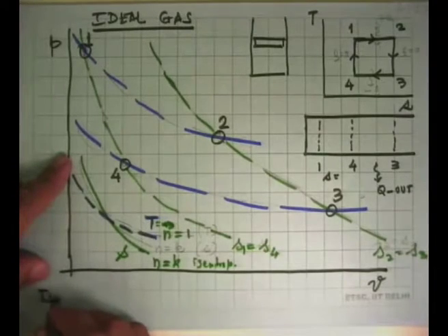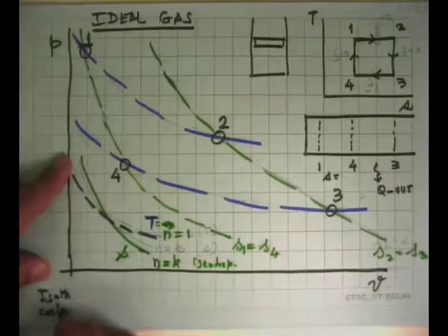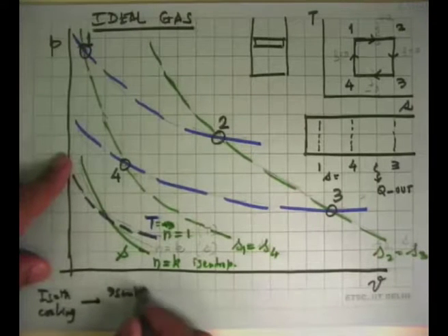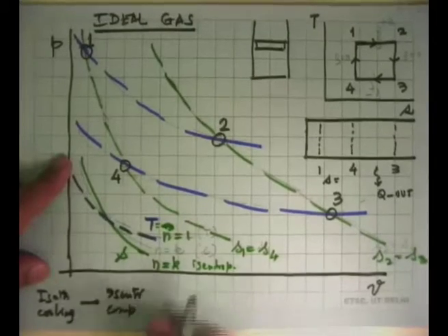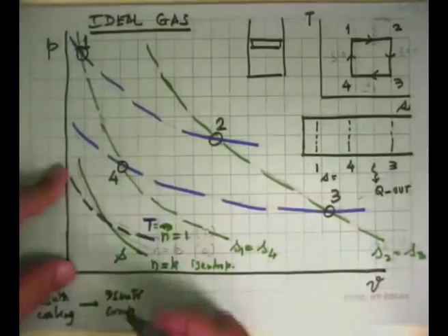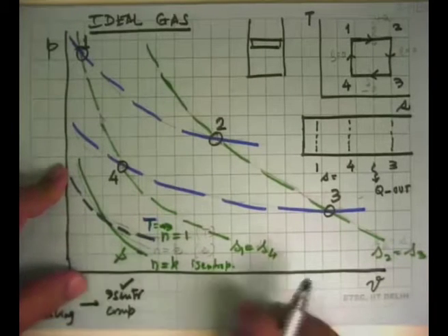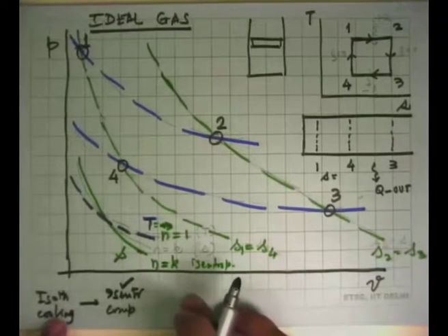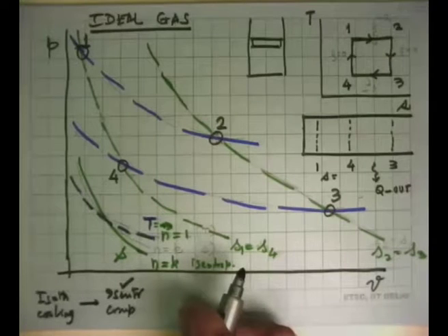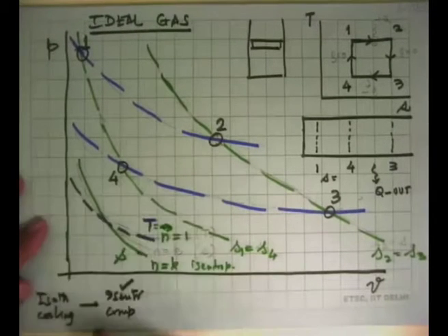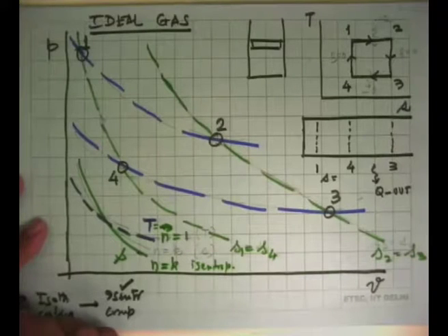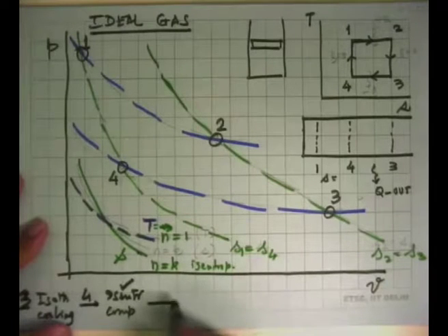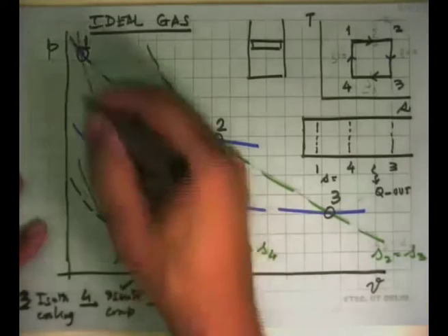So the first part was isothermal cooling while the piston is moving, followed by isentropic compression, which practically, if we do the best we can, I can get very close to. That's something we can get close to. This is a big problem: you cannot have that much heat transfer taking place from a cylinder in a very short period of time. That brings us to state 4. So we started here, we can call this state 3. It came to 4 as an isothermal process. Now 4 comes to 1. So that was the isentropic compression.